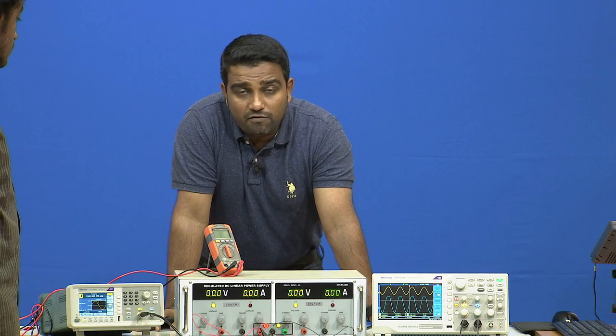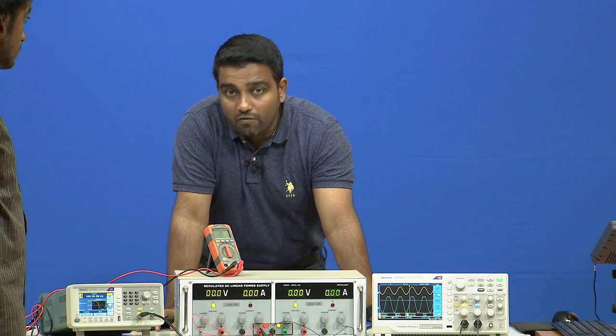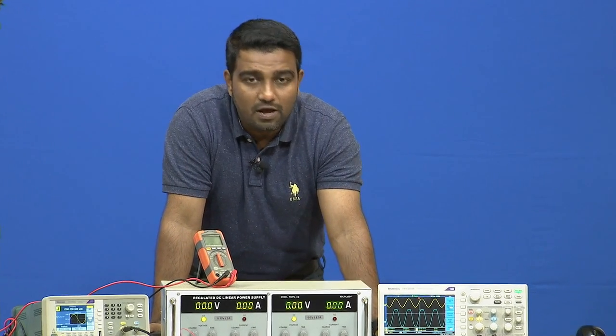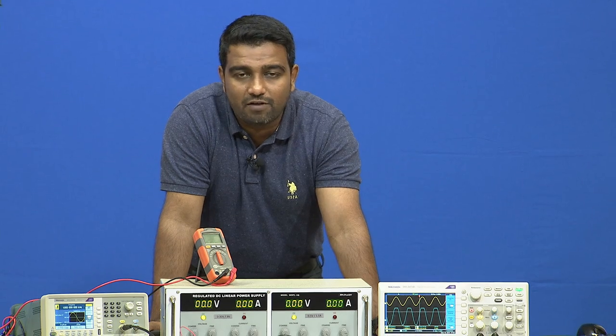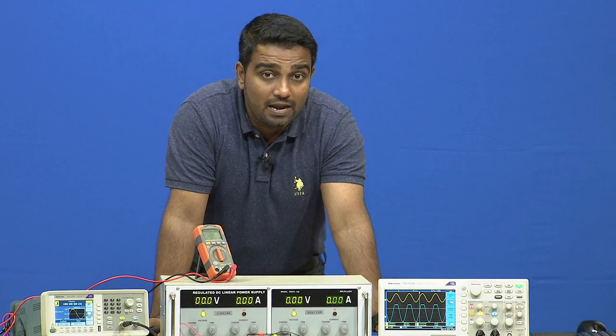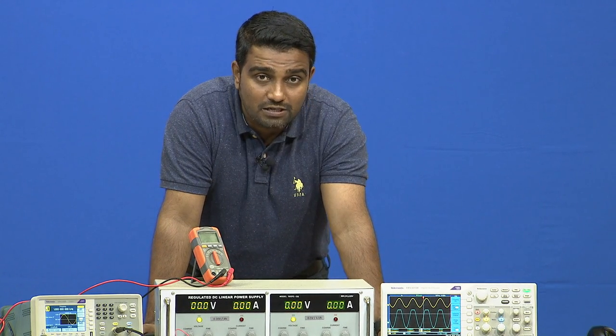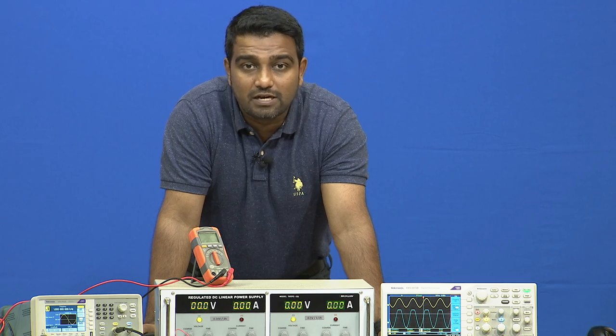So, what we have found? We have found that if we use an inverting amplifier we see 180 degree phase shift, and if we use a non-inverting amplifier we see 0 degree phase shift. In both cases, when we apply the input signal and we have a gain which gives an output signal more than the bias voltages, that is plus minus 15, we see a clipping, right.